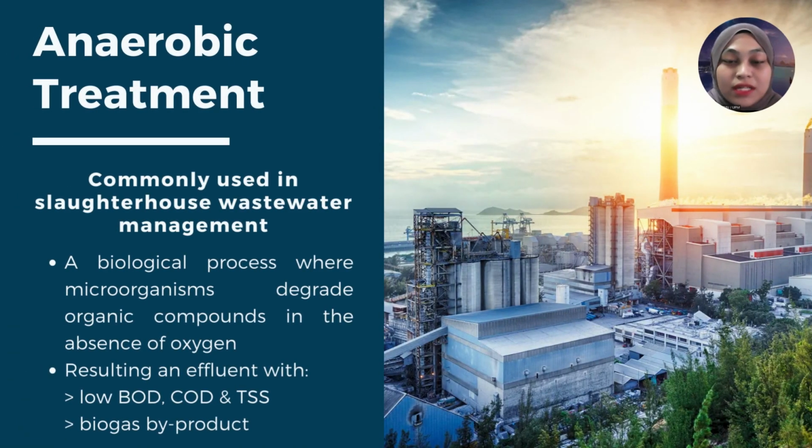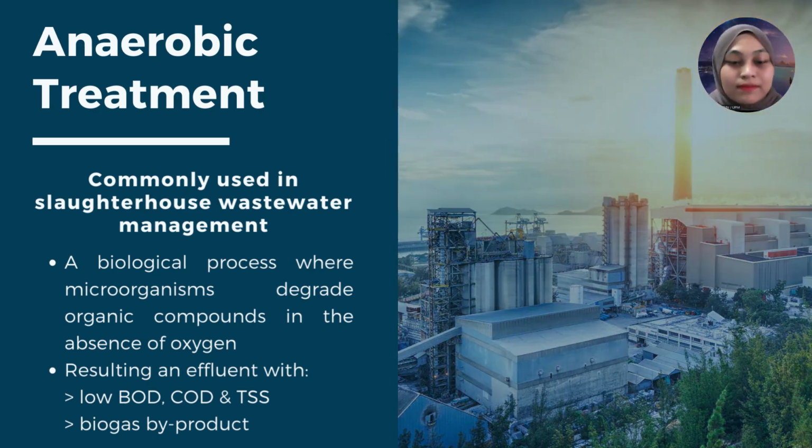Thank you, Azim. So the next treatment is anaerobic treatment. This is a biological process where the microorganisms will degrade the organic compounds found in wastewater in the absence of oxygen. This treatment is usually found in slaughterhouse wastewater management. The result of this treatment, the effluent discharge, will be low in BOD, COD, and TSS, which is total suspended solids, as well as a biogas byproduct.